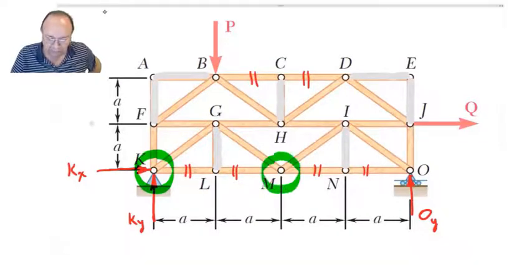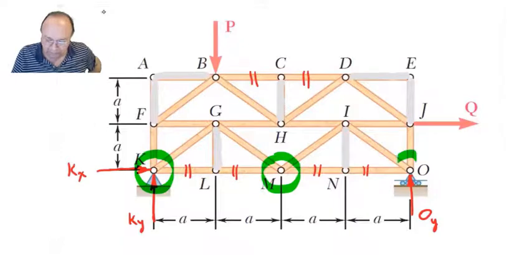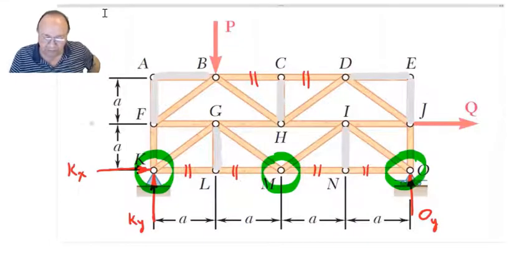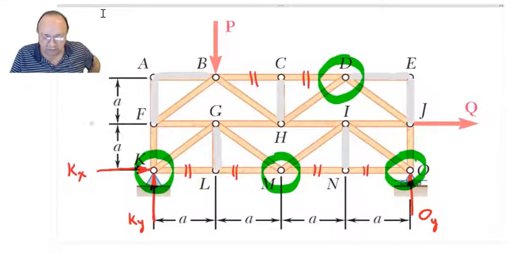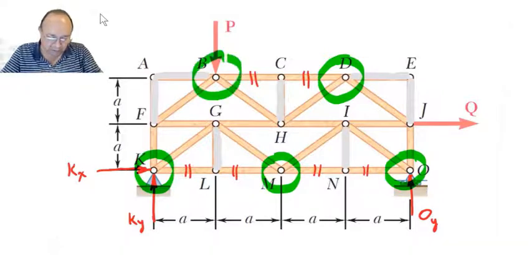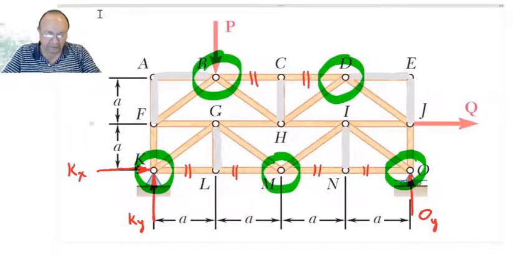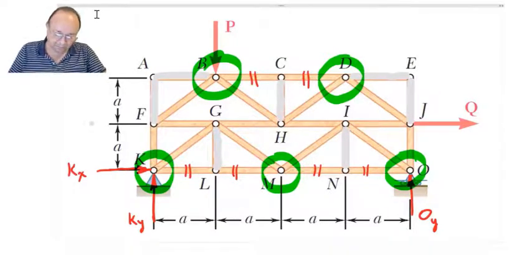This one 4 forces, this one 4 forces, this one right here 3 forces, but we don't have collinear forces in order to say that one of them can be 0. And this one here 3 forces, but none of them are collinear, so nothing else we can state here.